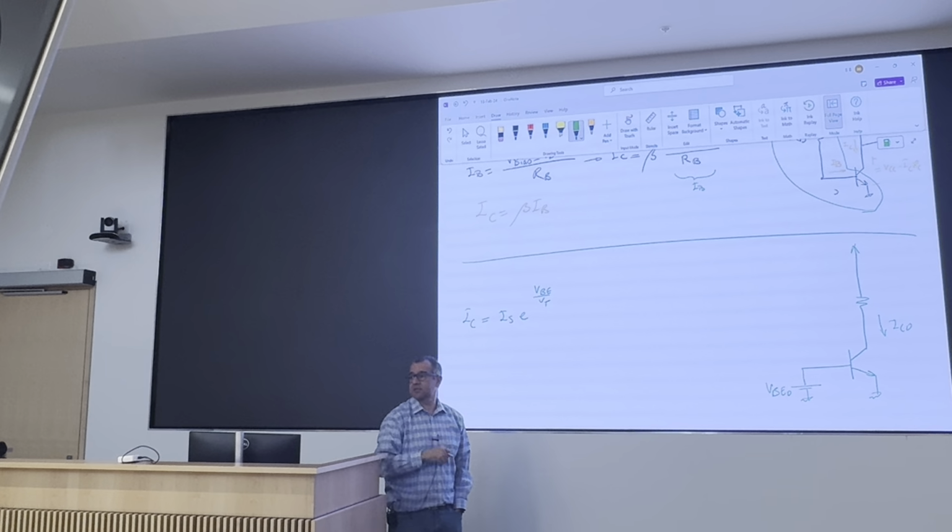So what you do is that you do not use this. Instead, we say, you know what, I'm going to use the power supply that I already have, and choose the ratio of RB2 and RB1 such that I get the desired VBE here. Right?